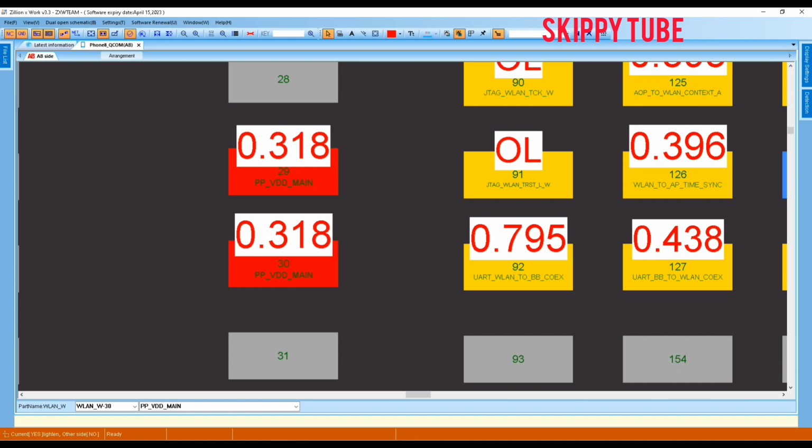That's the Skippy test, and all of them need to be checked. This is the important part. First is checking. If you find the issue, fix it, software or hardware, that's it. But if you want to check any phone, when you remove the motherboard, you need to check these four passes. And you see, if it's checked like that, it shows the fault in there. VDD main is showing the short circuit in there. Okay.